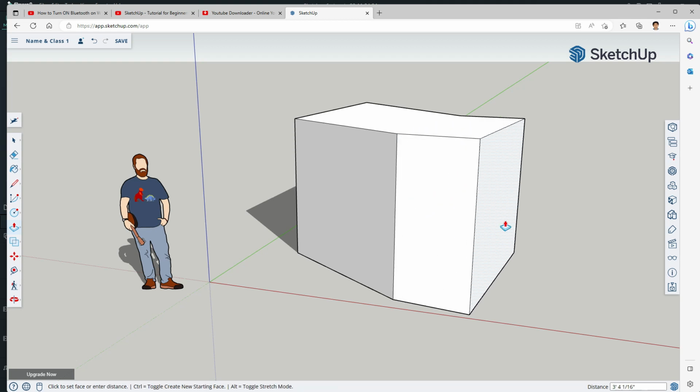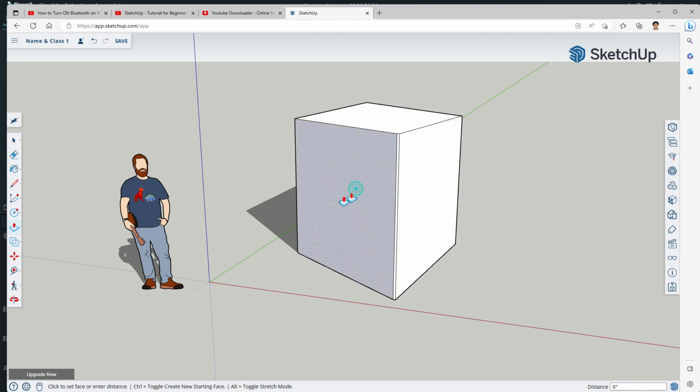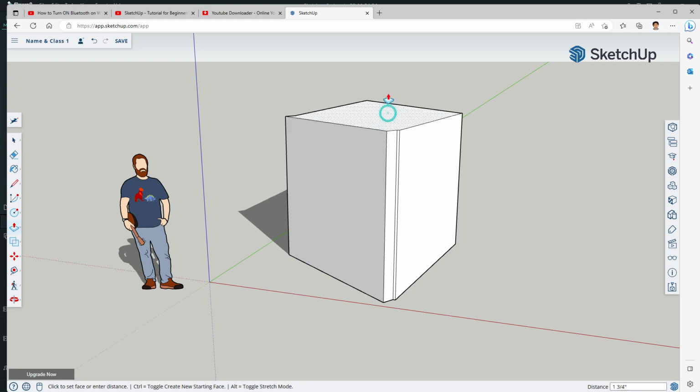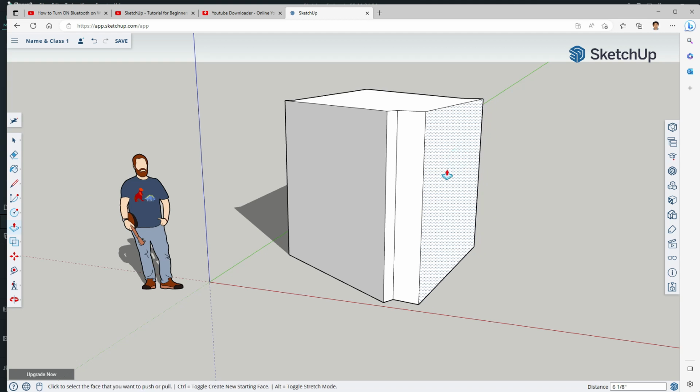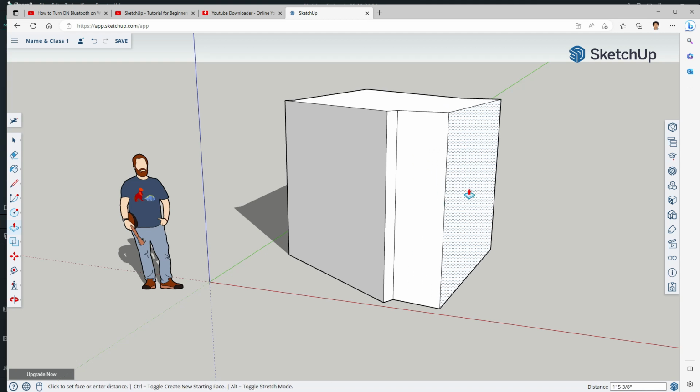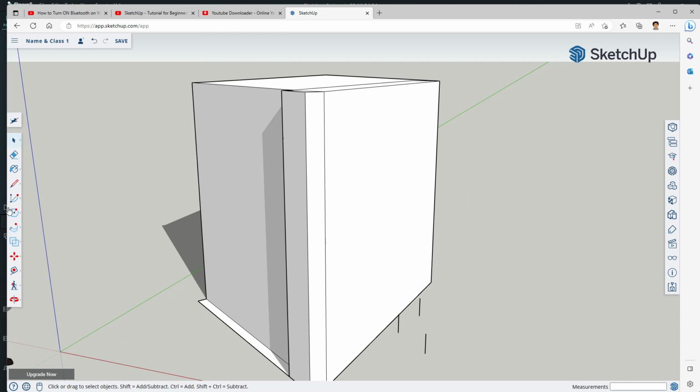You can see, now whichever place you want to drag or draw, you can do it. Like you make this small shape and then you use the push and pull. Then the follow me tool will give you the direction for 2D and 3D, in any direction you want.